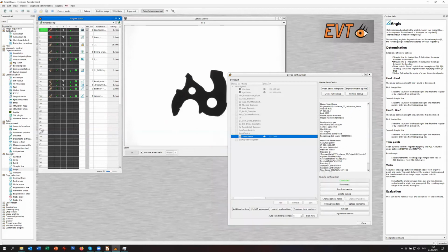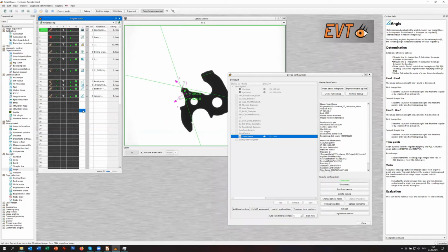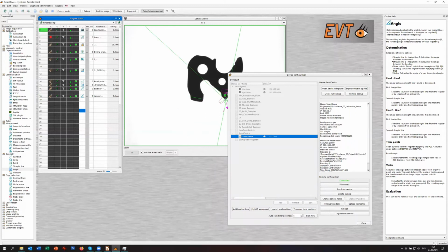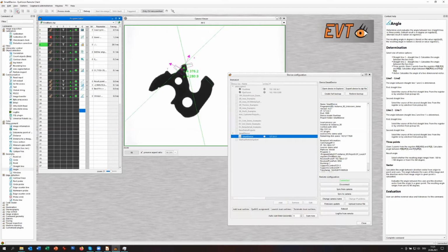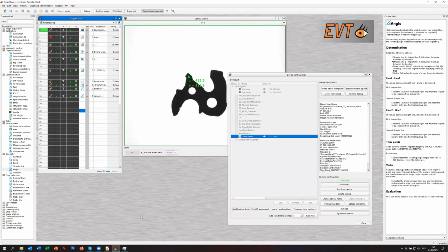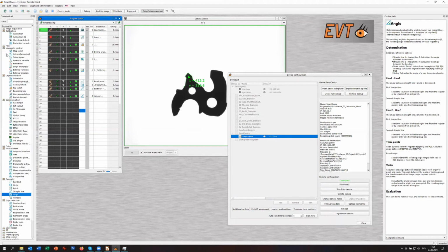Then let's run it and see. Now we are always in the tolerance, so we have to make the tolerance smaller, whatever. Depending on that, you could set the output commands here. That's what most of the smart cameras have, besides the Ethernet connection. You can simply control the I/O lines.